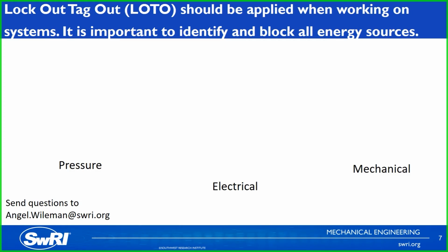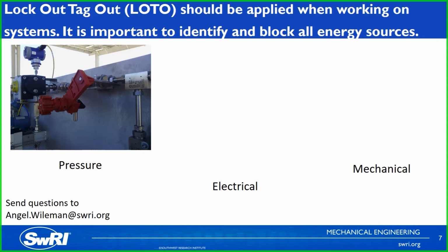And one other safety thing that I'd like to talk about is lockout tagout. We are doing a pretty good job at this, especially in the initial design phases for each one of these. We really sat down and identified how we can block out all energy sources when people are working on this. Some of the big energy sources from a fluids perspective are first pressure. Lockout tagout control of pressure is often done by closing valves and putting lockout devices on them that isolate part of the loop from a pressurized source.